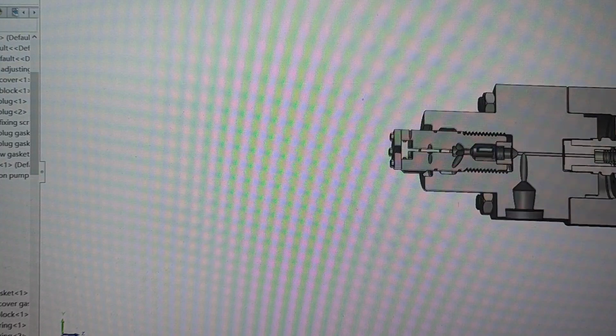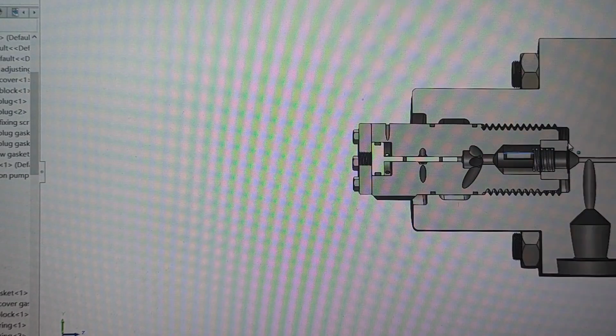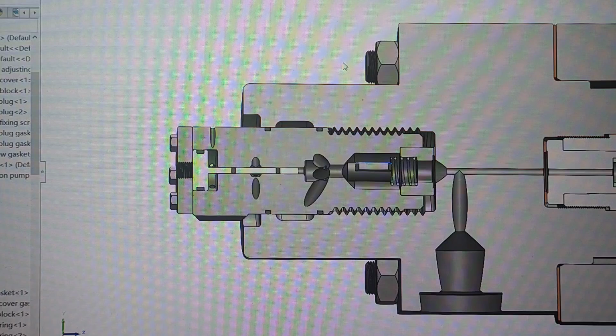So that actually means the high pressure pump no longer supplies the fuel to the injector when you supply the high pressure air to this puncture valve. Alright, that is used for the air start procedure of the main engine or the emergency stop of the engine.